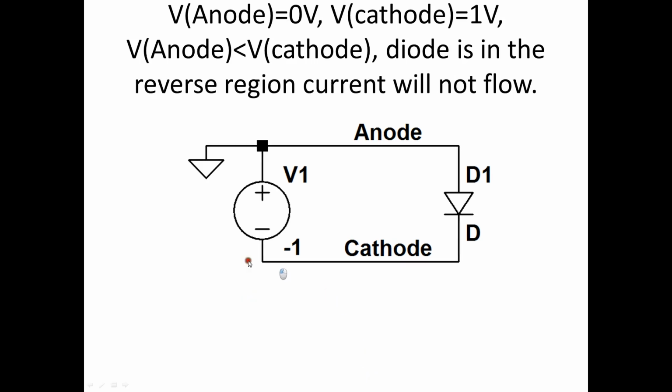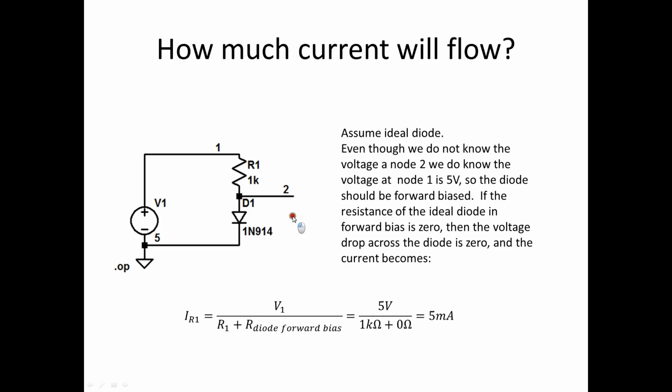All right. And just to round it out, we've tied the anode to ground, and we have a -1 battery voltage, but I'm going -1 from ground, and so in fact this is at a higher potential than that, and it's reverse biased. So the cathode is actually at a higher potential than the anode because of the definition of these voltage sources. Okay. Now let's put it in a real world example.